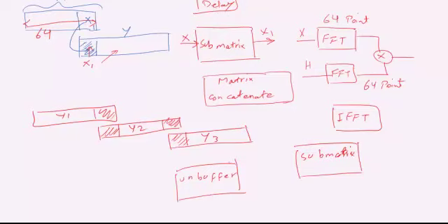Now you have to put the smaller blocks back together to create the large block. The output of the unbuffer goes to the DAC, and that gives you a signal at the output, and then you can connect that signal to the oscilloscope to be able to see the output.